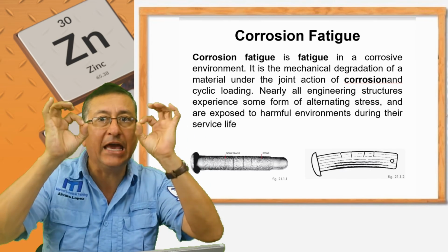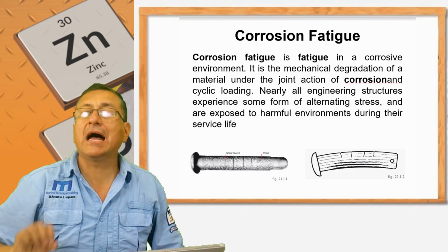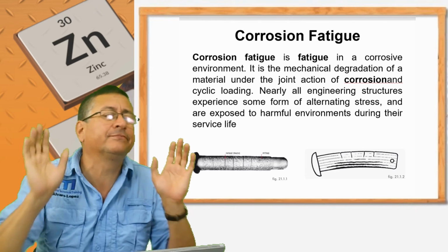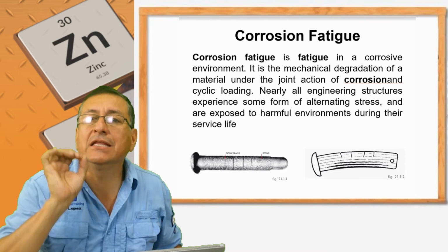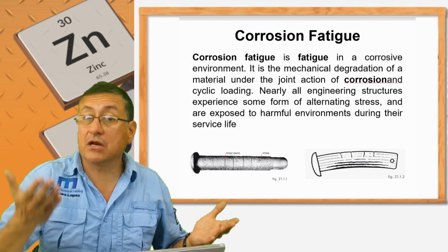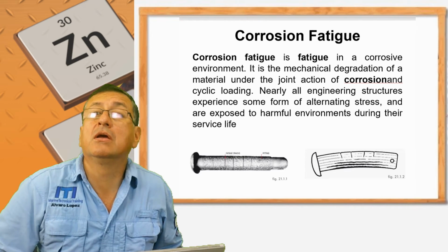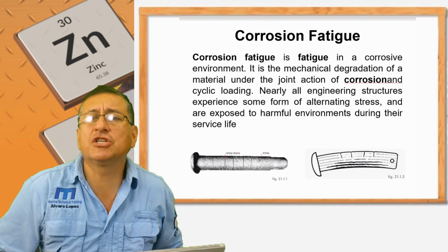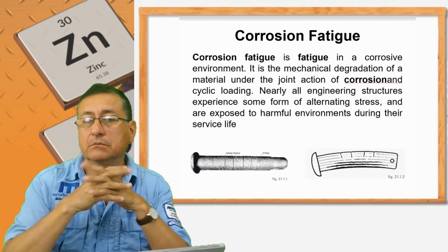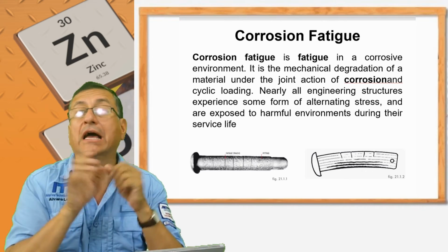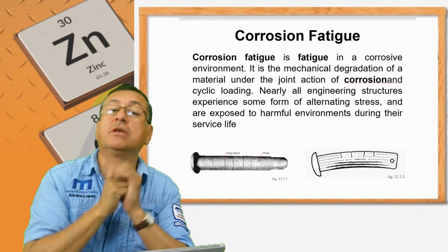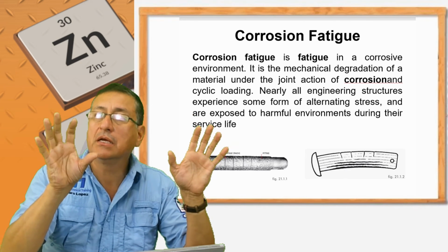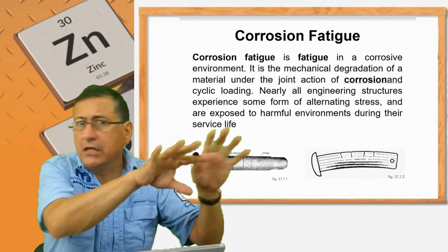And install gauges and meters. I have analog meters, but the needle moves a little. You need digitals, because with digitals you can verify. Remember, you need more than 0.001. With a needle gauge, it's impossible. You need a digital. For that reason, in the demonstration, I put my digital multimeter, because with the digital you can read. Install digitals in the AC and DC panel, in addition to the other ones.